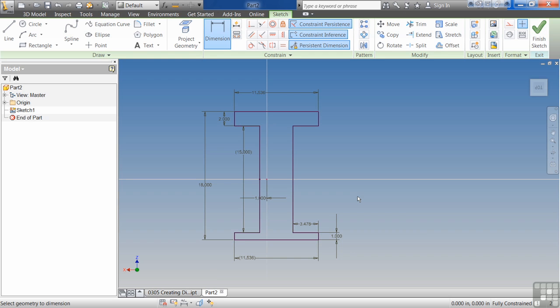You always think, oh, I'll never come back to this sketch. Once I create it, I'll be done. But there'll always be something you'll need to come back and do. So try to make sure that you limit the amount of dimensions and constraints and do it in as few steps as possible. One of the things I always tell my students is whenever you dimension something out in a sketch now, go back and look at it a year from now, and you'll laugh at how much you've come in a year's time because you'll use so much fewer just from experience. It's one of those things you need to play with and get good at. And that's pretty much it for the basic guidelines.